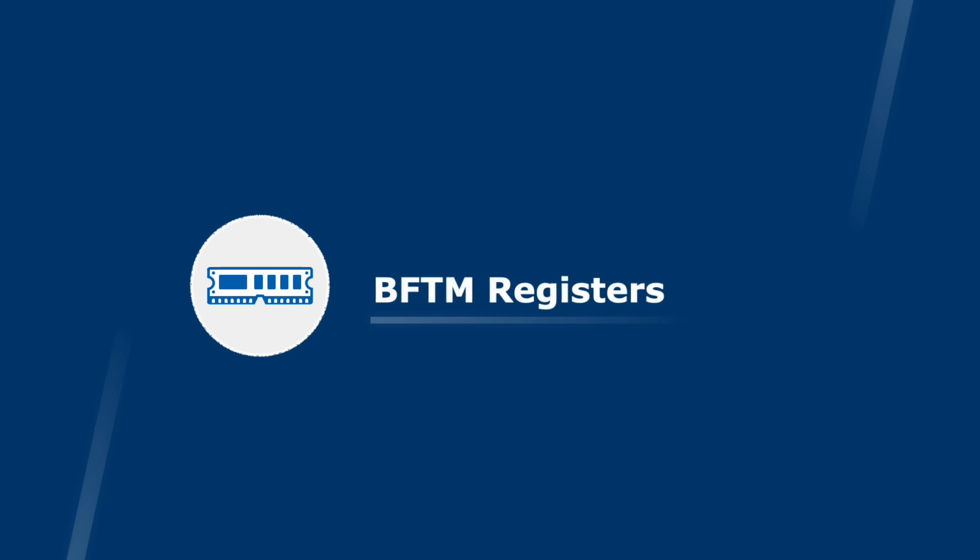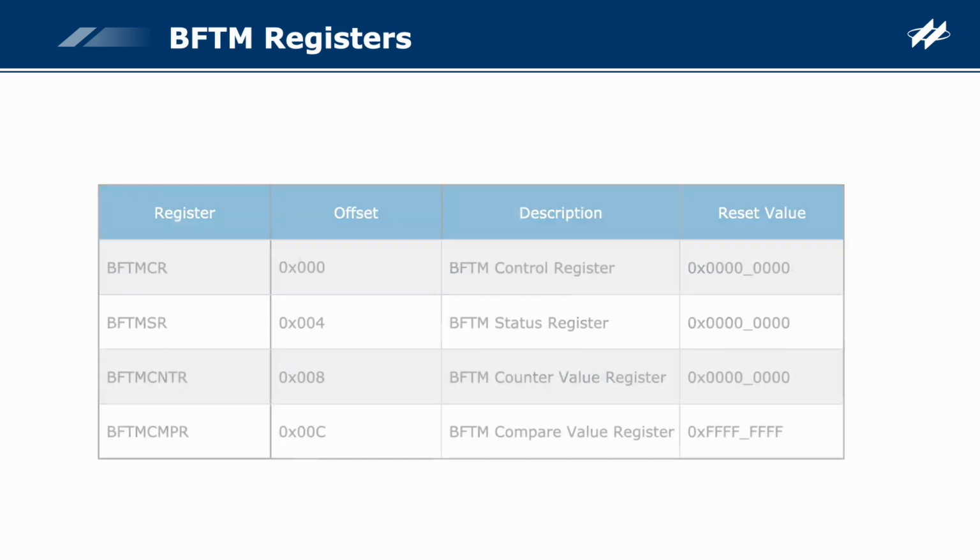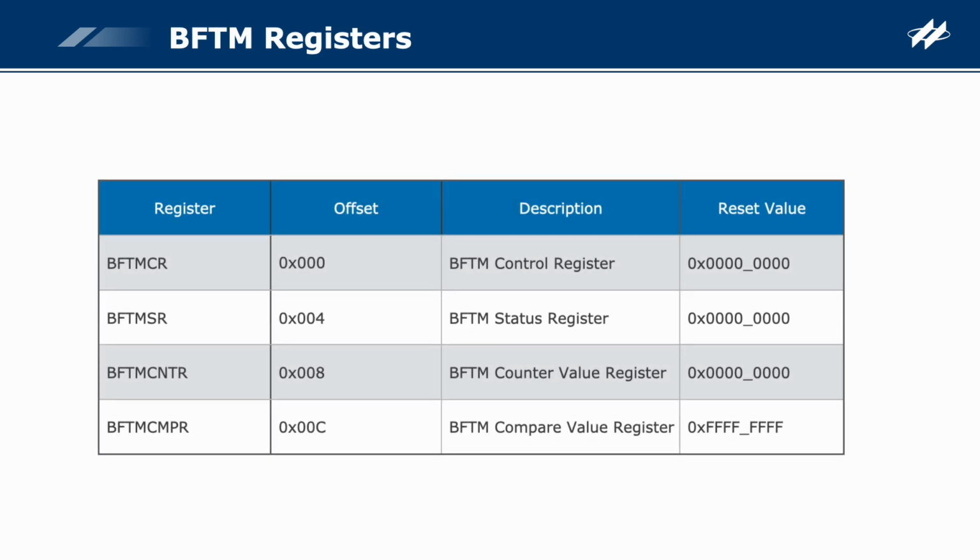BFTM registers. Then, we'll briefly introduce the BFTM-related registers. The BFTM control register is used to configure the BFTM counter, including counter enable control, counter operating mode selection, and interrupt control.